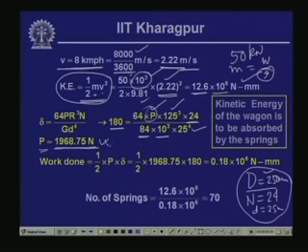So, this is the value of the load that can be applied to the spring so that the deflection criterion is satisfied. And as I said, the kinetic energy of the wagon is to be absorbed by the springs by applying that load and allowing that deformation, which we call the work done by the spring.